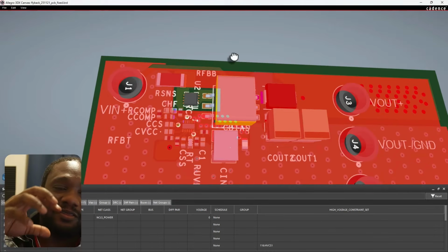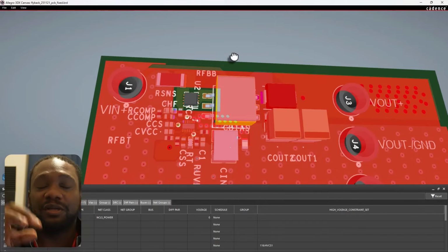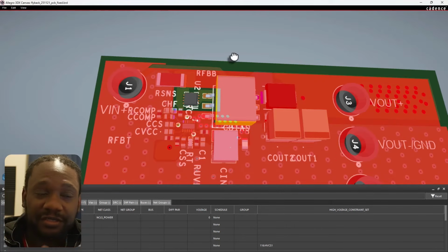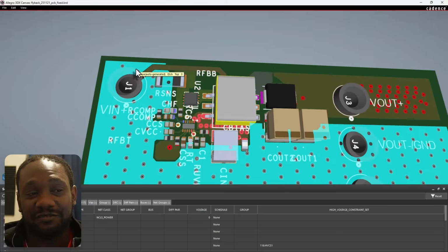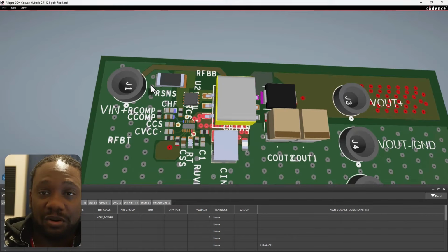The current and the fields coming off of the switching current will immediately go to the lowest impedance path, and usually that's the lowest inductance. With the return path right underneath there, it's gonna, boom, find that quickly. And with the stitching vias to ground as well, that's gonna drop the inductance and impedance even more, which is going to attract that field and make that EMI vanish.